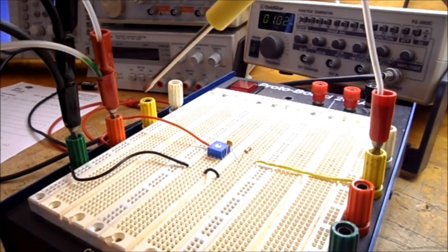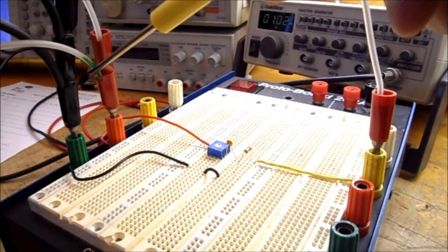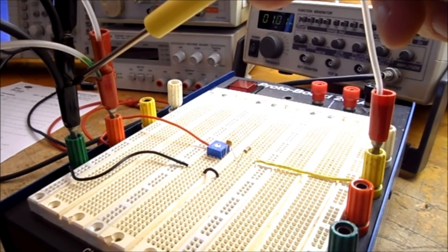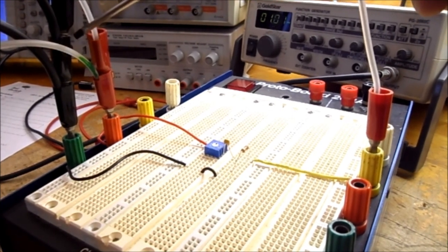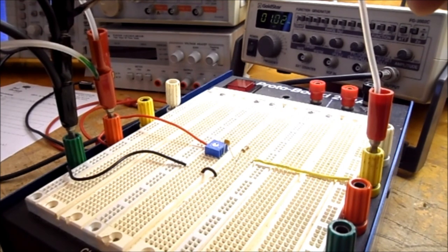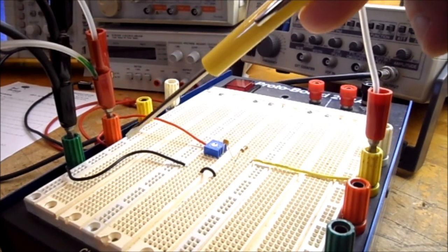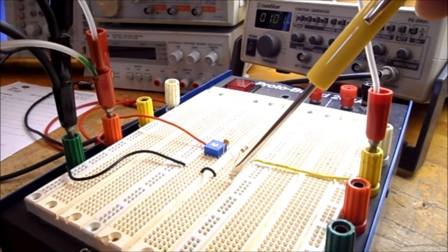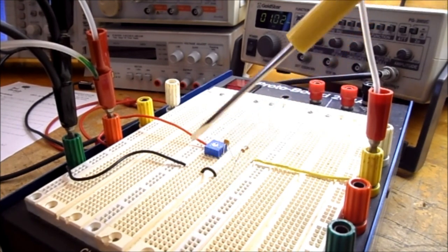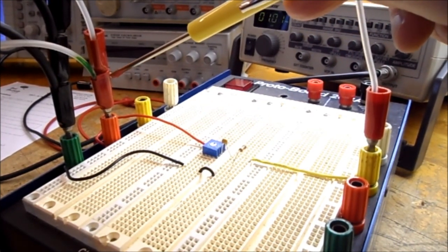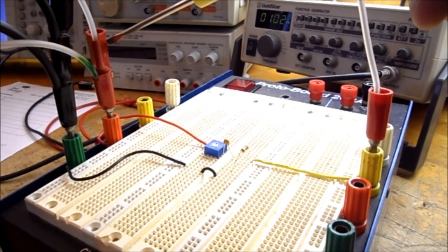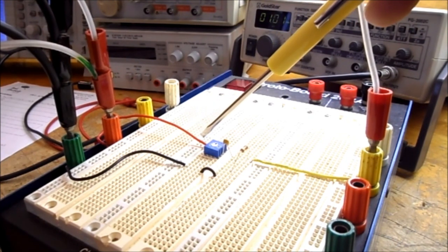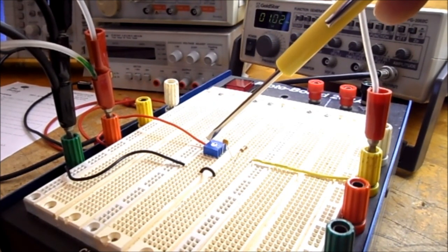So I just wanted to show you on my circuit the common of the function generator and the output of the function generator, the common of channel 1 and channel 2, so all the black leads go together and they join at the bottom of my 1K ohm load resistor. The output of my function generator and channel 1 of the oscilloscope go to the top pin of my potentiometer.